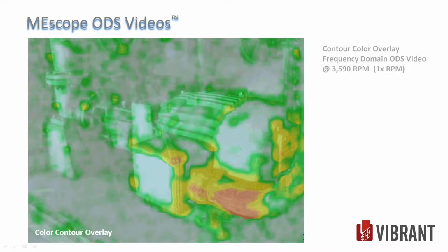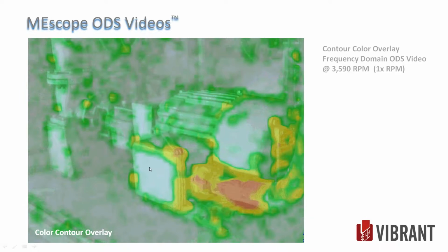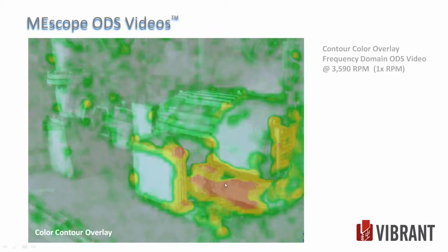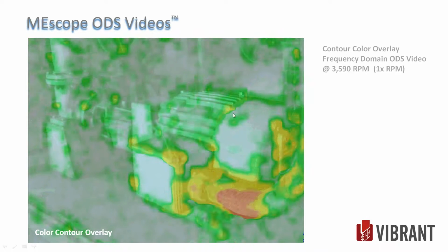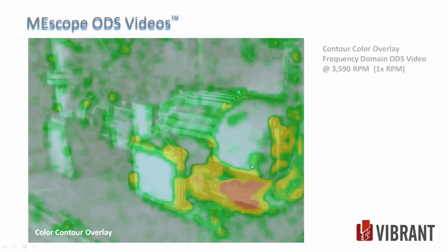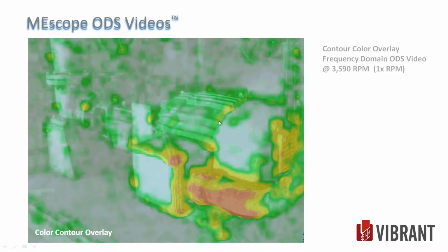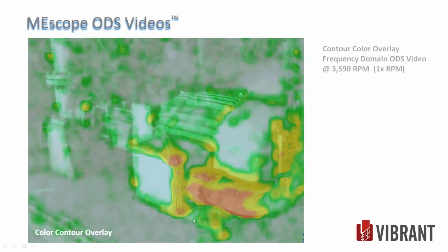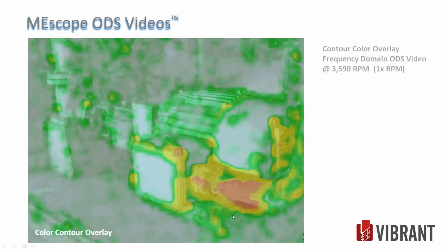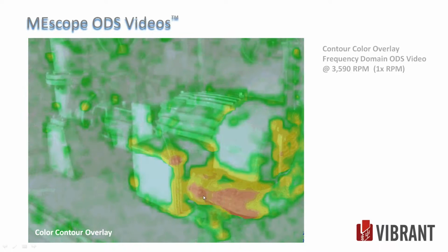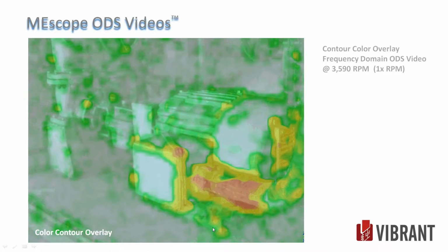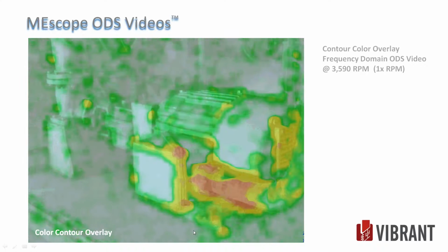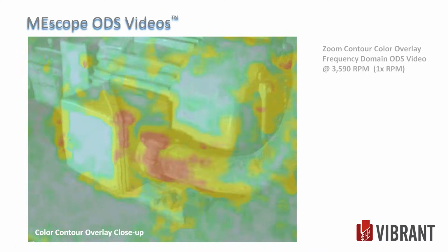And this is showing me the same motion, but it's showing where it's all peaking out. A lot of the motion is in this electrical box, and it's wagging a little bit as the entire motor kind of goes corner to corner rocking. We originally thought it was a misalignment, which has some similar motion, or a soft foot condition where we didn't shim properly on the feet because there was some motion down here, but it turned out to be something a little bit different.